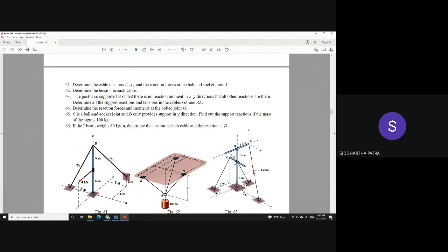Okay, get the equivalent force system about A. The resultant force and the resultant moment. Or the equivalent force and the equivalent moment. Let that be at A. Both of them must be equal to 0 for equilibrium. That's the idea. That's what we have been doing for all the 2D problems. So it's getting an equivalent force system. You have done that for 3D problems, no issue. The idea is just that the moment will have 3 components and the forces will also have 3 components, unlike 2 and 1 in 2D.